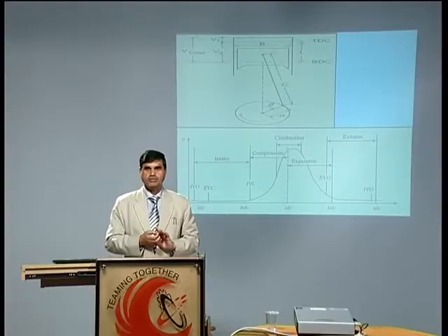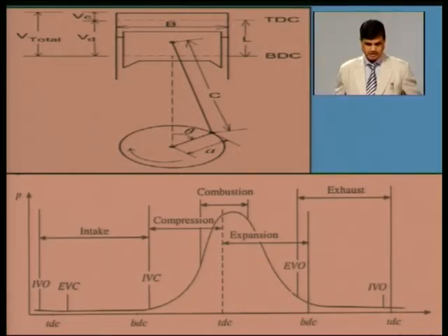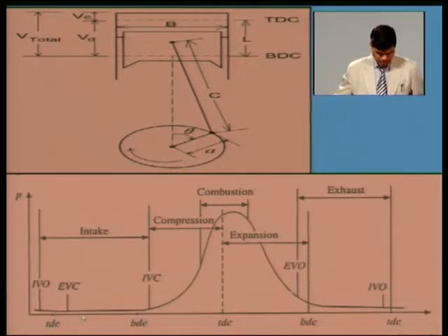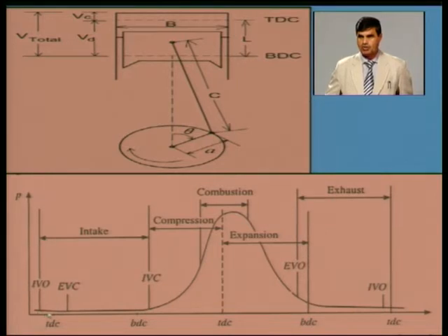This I am showing you is the pressure variation when the piston is moving inside the cylinder, how pressure is varying inside the cylinder. You can observe from here, somewhere I am showing you TDC, another side BDC. So TDC, BDC, movement of the piston in the suction stroke, the intake stroke. In the suction stroke, more or less pressure inside the cylinder is atmospheric, slightly lower than atmospheric, low pressure, no variation. The piston is going in the downward direction, and at the same time fresh mixture is entering into the cylinder. So more or less pressure is constant.